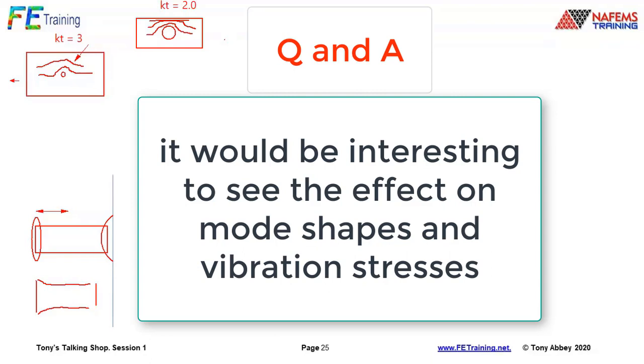And then if we are using, let's say, a modal method to establish stresses at a particular time point, using a combination of those mode shapes, that's a different question. So I think the question probably plays more to recovering stresses once we've got our dynamic results coming out. And then everything we talked about statically is also true dynamically.